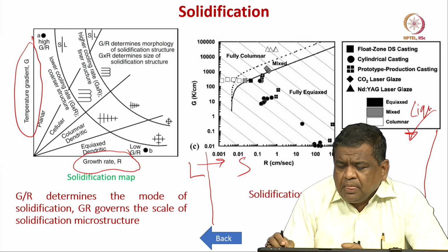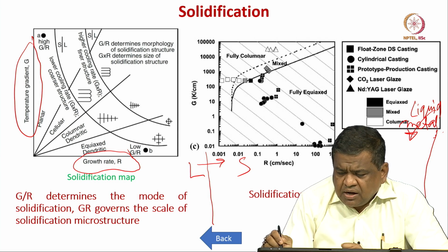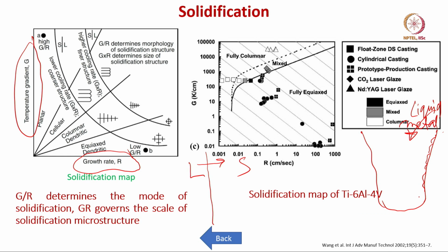During conventional casting processes, the mold wall provides sites for heterogeneous nucleation. And after this, the interface grows in this direction. The same is true of this interface, which grows in these directions, and from the base the interface also grows in these directions.